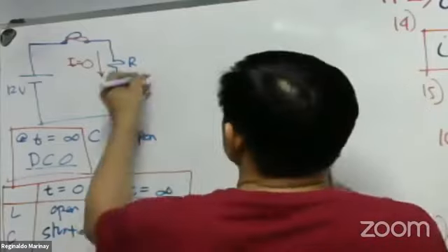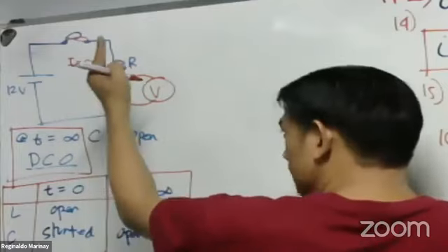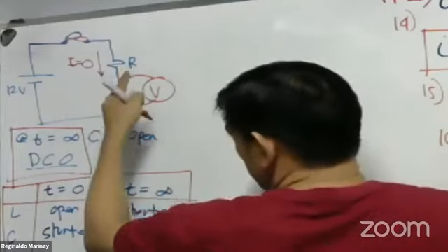There is no voltage drop here because our voltage drop is IR, 0 times R, and any value times 0 is 0. But the voltmeter reading here will just be connected in parallel with the source of 12 volts. Did you get that? Is that clear? Maliwanag ba yon?